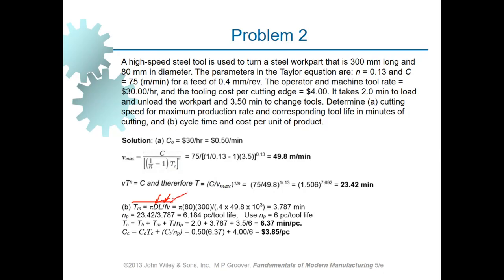And then feed and also cutting speed. These ones are also available. F is given, phi is just computed up here. So we have got phi, V computed up here, F is given, which is speed, D and L are given. So we have everything in order to compute the value of machining time. This is the time of machining, excluding loading and unloading, excluding, say, tool changing time. However, loading and unloading is also given, and tool changing time is also given.